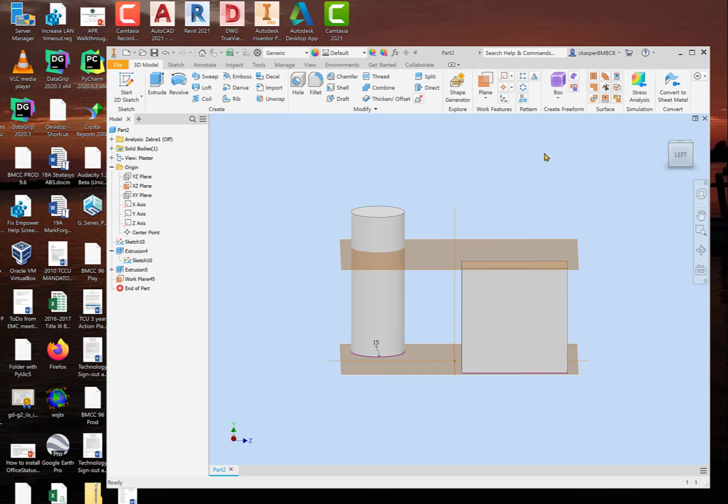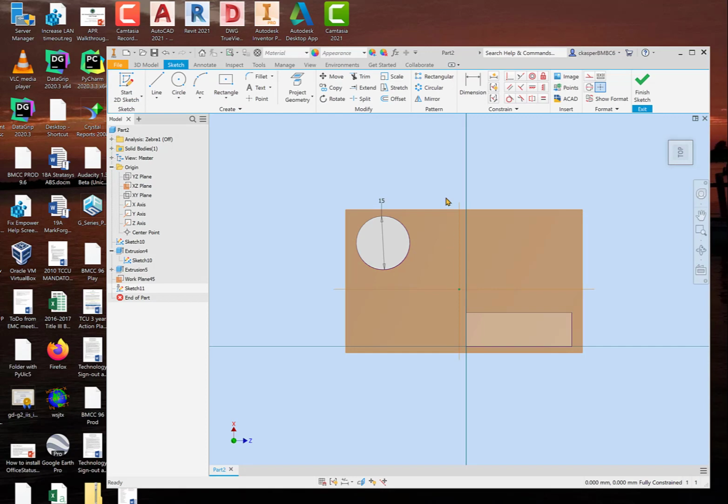Well, here's an interesting thing. I can sketch up. If I go into this plane right here and I go into sketch and I choose this plane right there to sketch on, there's something here called a point. I can throw a point here, and I can throw it here, and how about there, and out here in the blue, and out here in the blue, and see that my plane comes out to meet it and surround it as I put them in. Now we're going to finish that.